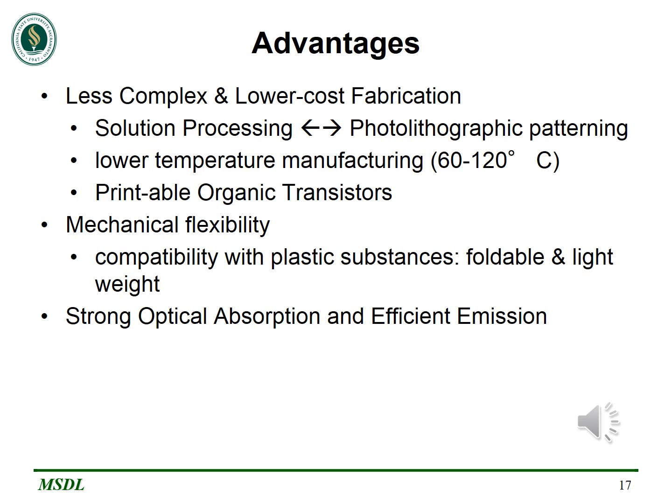In this slide, we are going to discuss the advantages of OFETs. OFETs are generally less complex and have low cost fabrication. We can manufacture them at lower temperature, and it has a printable organic transistor as well. Its mechanical flexibility is high. Compatibility with plastic substrates is high. It is foldable and lightweight. It has strong optical absorption and efficient emission as well.